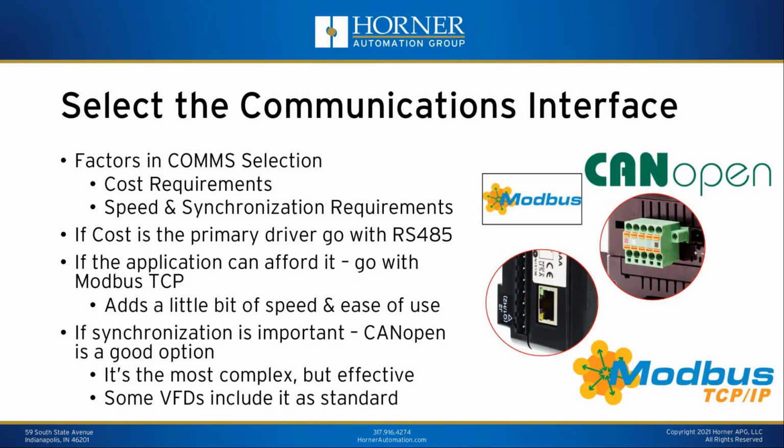Now, if the application can afford a little bit of extra, because it's usually not 100% free from a drive standpoint, then bumping up to Modbus TCP is a good idea. Oftentimes, it adds a bit of speed and a bit of ease of use. The wiring is certainly simpler as opposed to having to wire up point-to-point wiring. However, you do have a requirement then for an Ethernet switch, and other components similar to that.